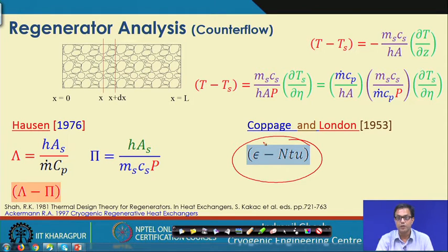We will look into the details of the definitions of epsilon and NTU, and since we are a bit familiar with this terminology, we will go into the analysis by epsilon NTU, and later simulate and design the fixed bed counterflow type regenerator by taking this approach.